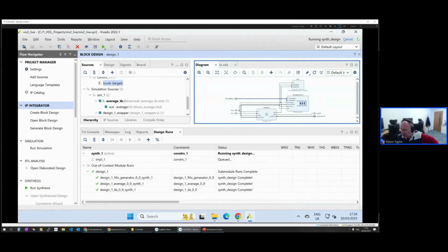So, Atarius, it's a good question, a good point. So you're saying that inserting the register in a long path will increase resource utilization, and of course it will increase resource utilization. FPGAs are generally logic register rich anyway. But you could also try to replan the floor plan by hand to try to bring those gaps together to try to remove the delay.